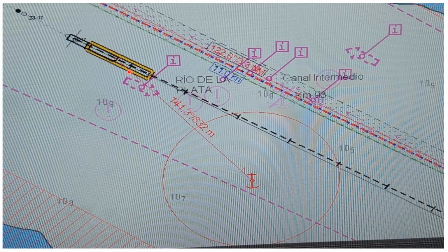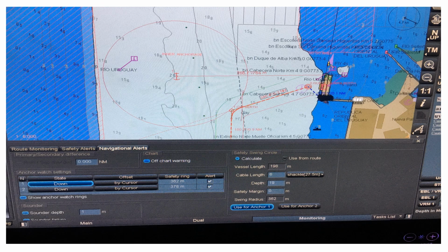You are not yet able to arrive in the anchorage area, but you want to have some course line laid out going to the anchorage area. So you have the bearing, you have the distance, then you can follow this one. Then once you arrive here, you drop your anchor, you remove this, and then you put down again. Once you have already arrived there, you put down.